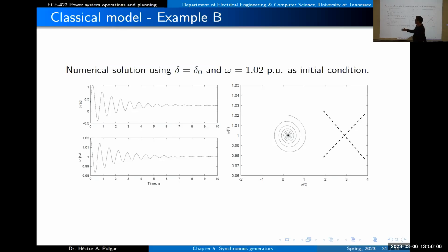Something that I didn't mention is that certainly you have oscillations here. But here the oscillation, we can see how much is the period. If we have the computer in Matlab, maybe we can look at this. But here you can kind of estimate what is one period and determine what is that time. Based on my appreciation of this plot, probably this is a little bit less than 1 second. So the period of the oscillation is less than 1 second. The frequency is a little bit higher than 1 hertz.